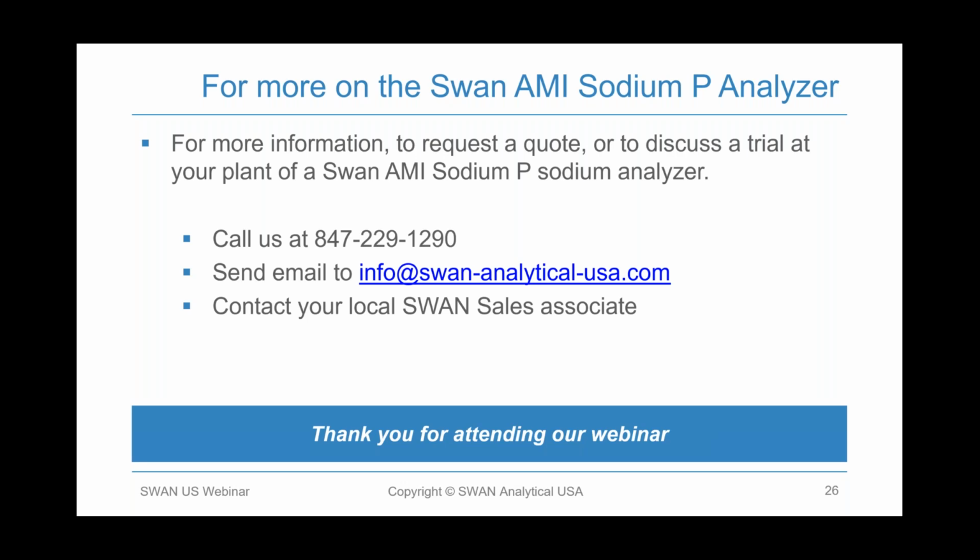Sodium analyzers and silica analyzers are monitoring, as we know, 2 different parameters. Then there's no relationship between the sodium and the silica that is in your steam water cycle, because there are so many different sources of sodium. It can be, like I said, a condenser leak. It can come from your makeup water. Therefore, monitoring the sodium is definitely recommended by EPRI and IOPS VGB.